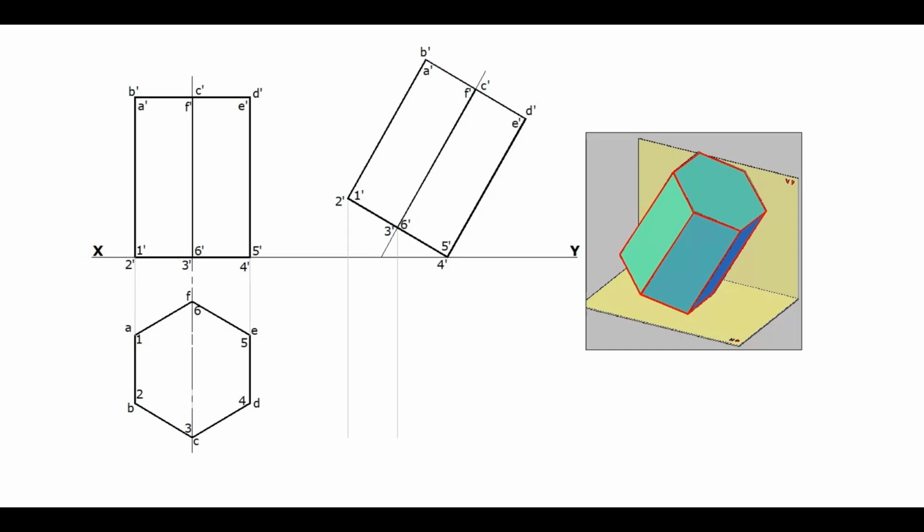To draw the final plan or second plan, project all these points below the XY line. Project all the base corners from the first stage plan also. Trace the corresponding points of intersection.